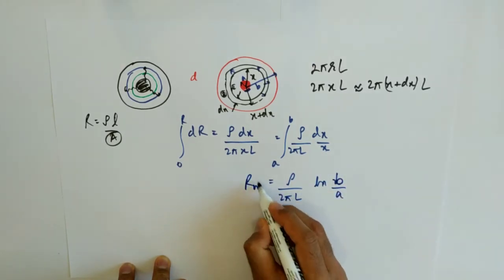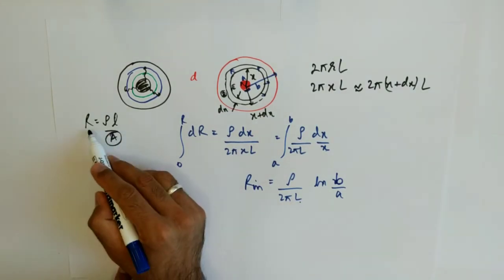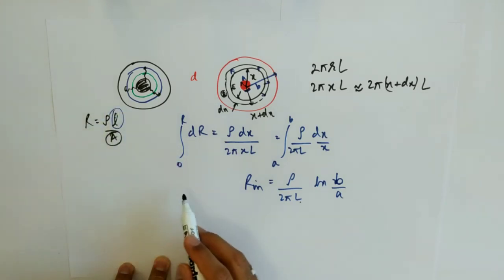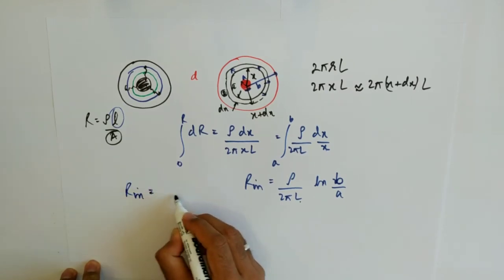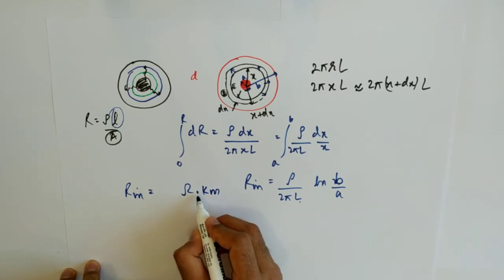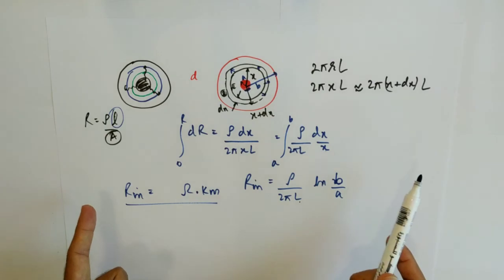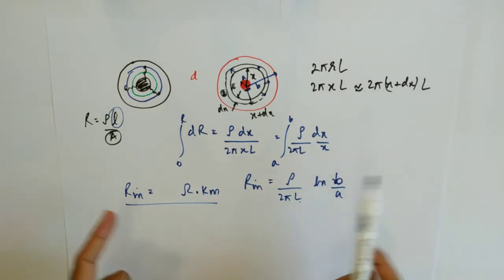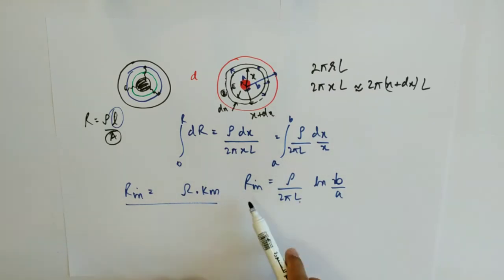So you see the insulation resistance or the leakage resistance here is inversely proportional to length, whereas the actual formula states rho L by A, that means directly proportional to length. That is why we get confused in writing insulation resistance for running rails. In the standard it is mentioned as ohm into kilometer, but generally we write ohm per kilometer. So remember this. This is also helpful when you see the measurement: for a longer cable, the measured IR value will decrease. Similarly for HV, a higher amount of leakage current will flow once the length increases. This is the reason why it happens, because resistance is inversely proportional to the length.